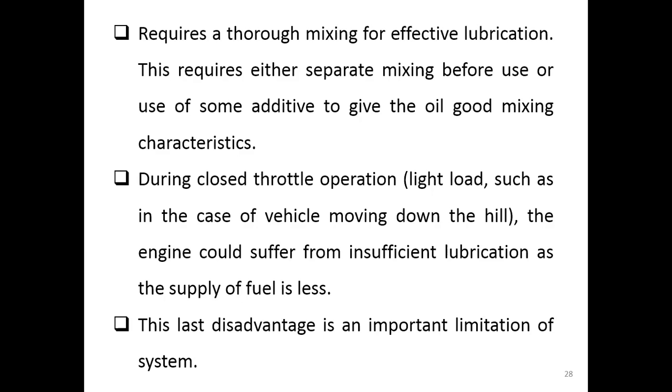And since the amount of fuel is less, it will lead to less lubrication oil. That's the reason why we don't have enough lubrication under the light load condition of the engine, because under light load, the supply of fuel is less, and that means the lubrication oil is also less.